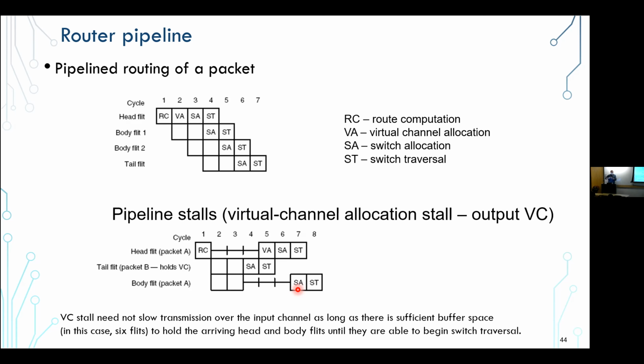It again has to do with the throughput and round trip. So you can't avoid Little's law any way you try, right? It's just that there are those different mechanisms that, for example, don't want to do the credit increment, decrement. They would rather send a whole bunch of stuff and then get ACKs for that, right? I mean, you see that example in traditional networking as well, where you just get a stream of ACKs depending on the depth of the buffers.